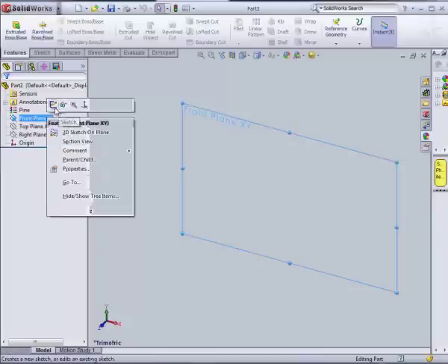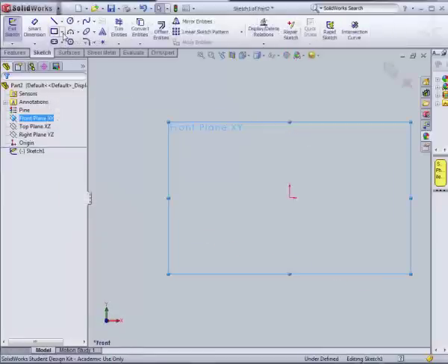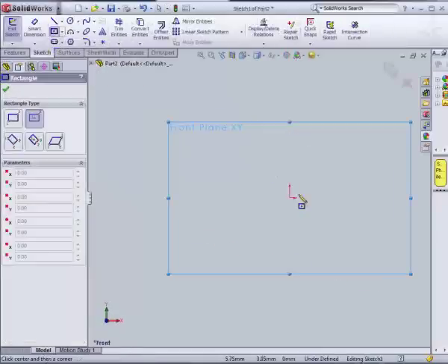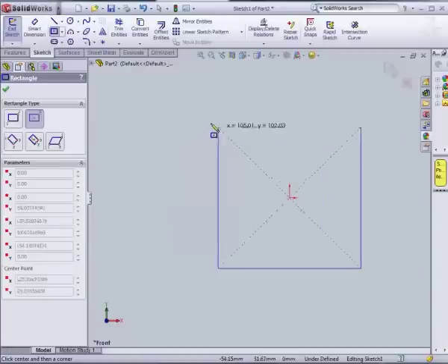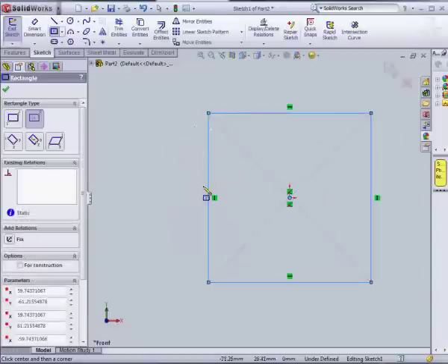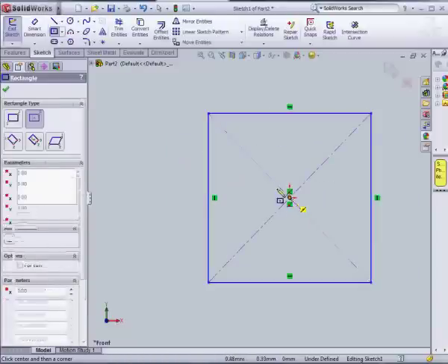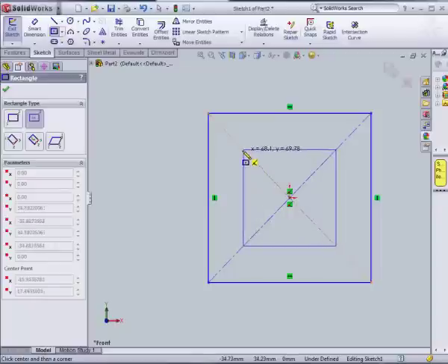and we'll try and model it this time a bit better. So open a sketch on the front plane and draw a rectangle. This time I'm going to use center rectangle and start from the origin. Okay, so any size. And I'm also going to sketch the cut as well in the initial sketch rather than having to add it later on.